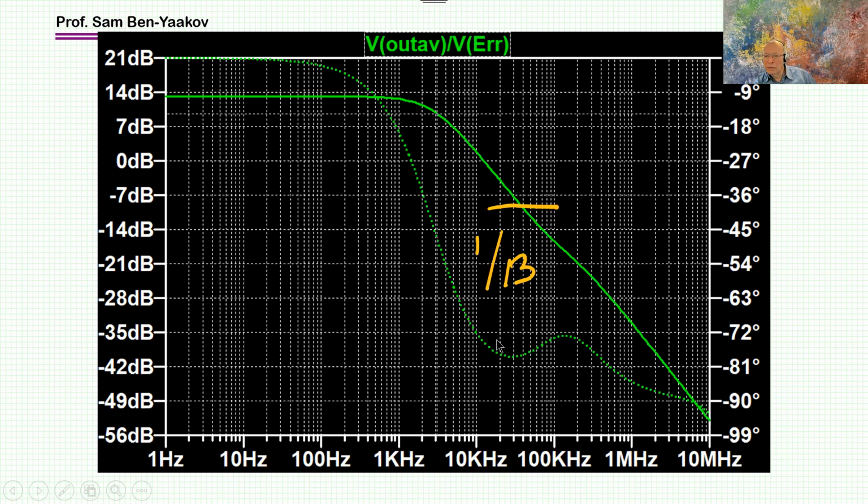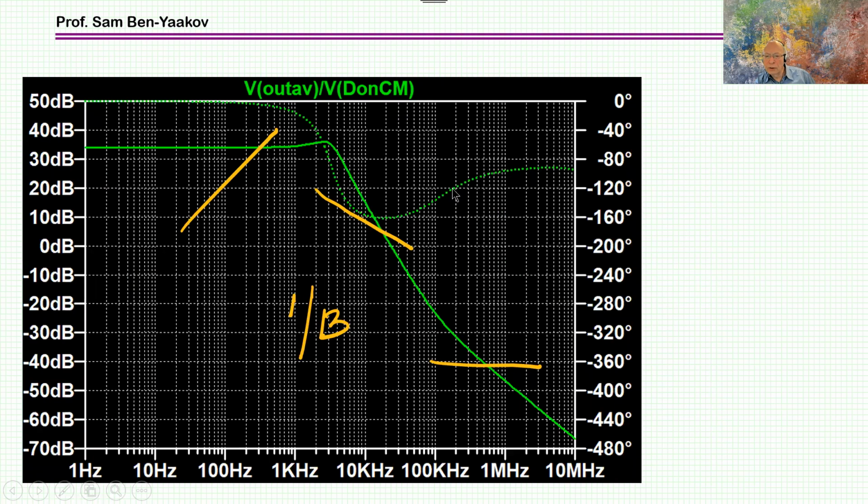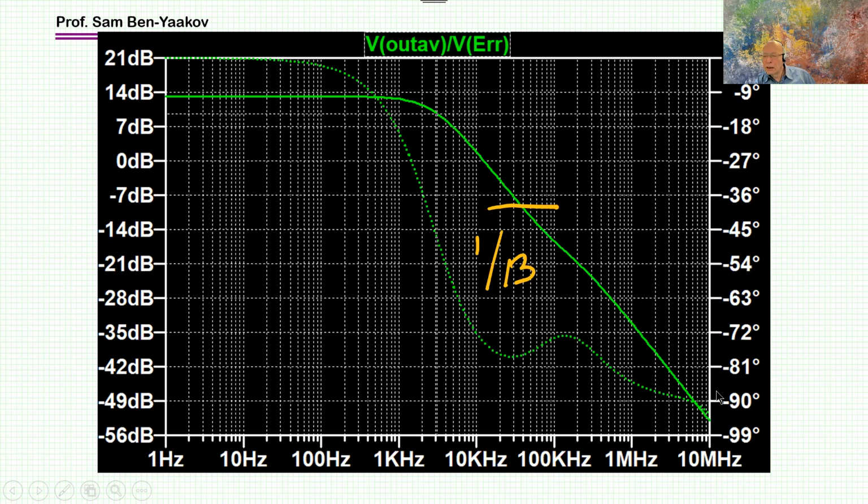It was earlier very low, 120, 160 here, and here the lag is much smaller, so it's more like a first order. Then we see the effect of the higher zero, which I'm not interested in. But I can see that I can very nicely close the loop here.